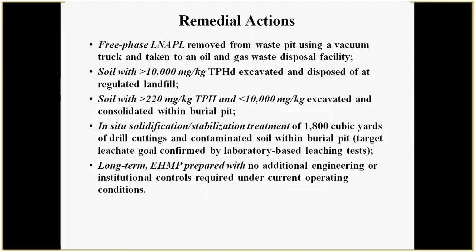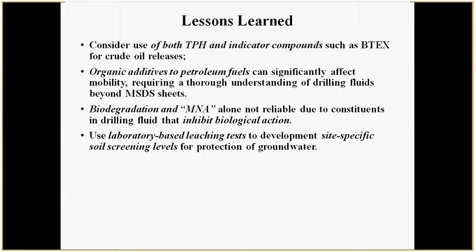Lessons learned: consider the use of both TPH and indicator compounds such as BTEX for crude oil releases. And also organic additives added to petroleum fuels, in this case, can significantly affect the mobility and increase the solubility of these fuels. Even though they're using diesel fuel in the drill cuttings for drilling, solubility is much higher than typical diesel fuel because of all the additives. This is something you have to think about and have a much more thorough understanding of drilling fluids beyond your standard MSDS sheets, or in a site-specific case.